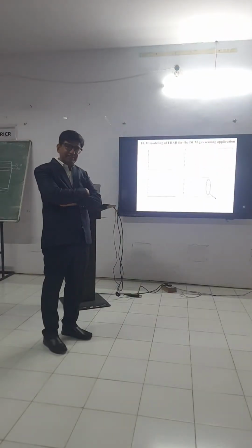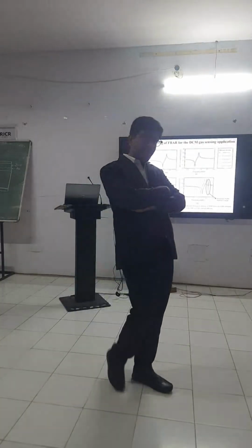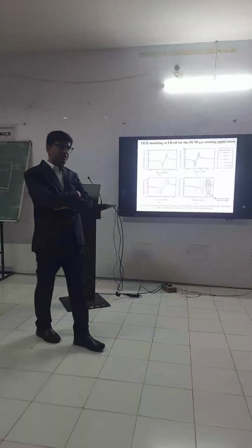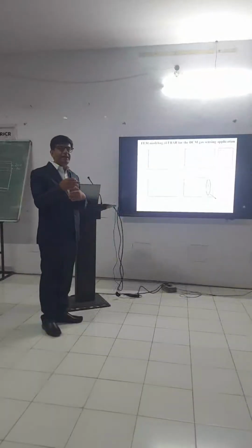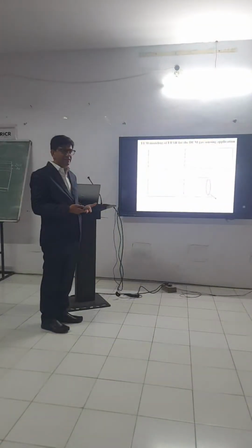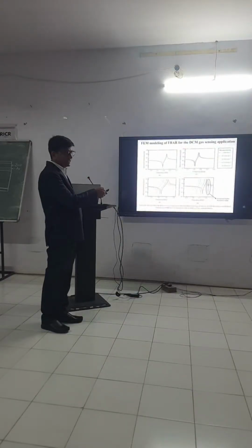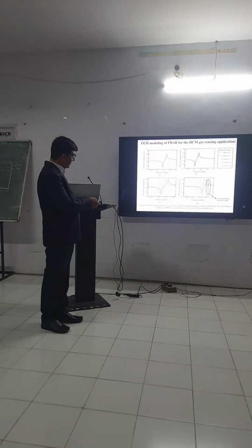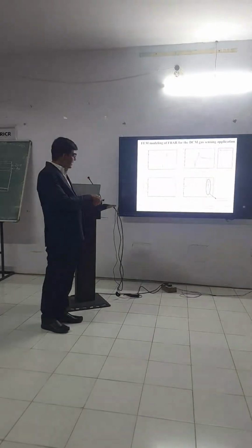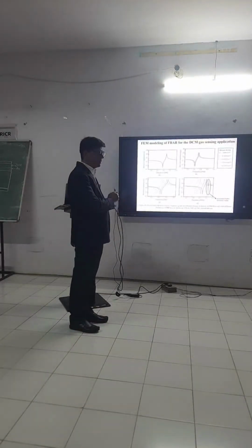What we want in our sensor is that it should give us a very high frequency shift without any higher harmonic mode. Clear? If my delay is more, then I can easily visualize my change in the concentration. See, in this case there is no change in frequency. Then how can you measure the concentration a particular gas gives? In 340 there is a change in frequency, but very little. But in 510 we have a very good shift in frequency as well as no generation of higher harmonic mode. So I optimize my thickness to 510 nanometer.